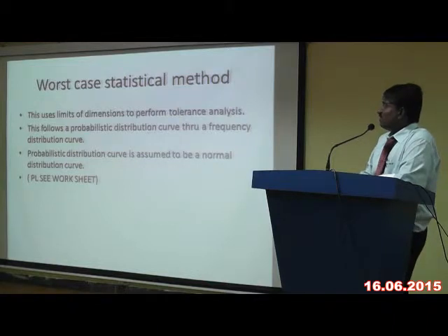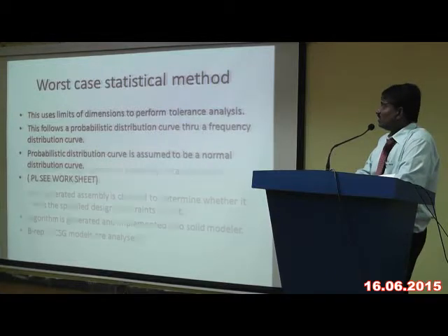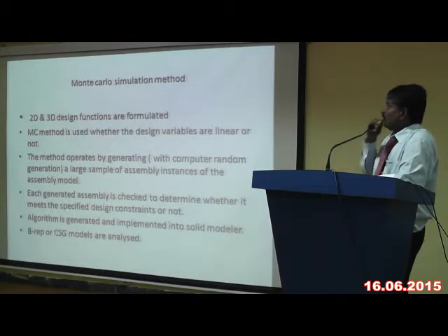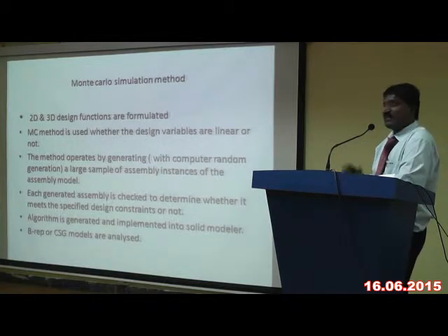This uses limits of dimensions to perform tolerance analysis. The statistical method follows a probabilistic distribution curve to a frequency distribution curve, and the probabilistic distribution curve is assumed to be a normal distribution curve. I have shown you the worksheet. So this statistical method will help you to bring out the difference. And in the Monte Carlo simulation method, two-dimensional and three-dimensional design functions are formulated, and the method is used whether the design variables are linear or not.